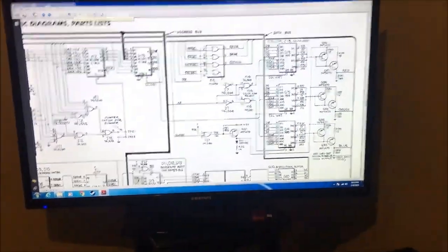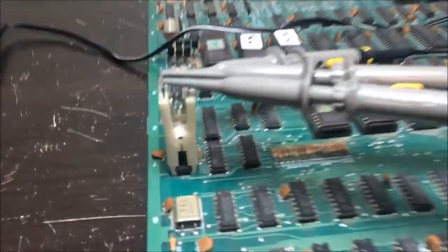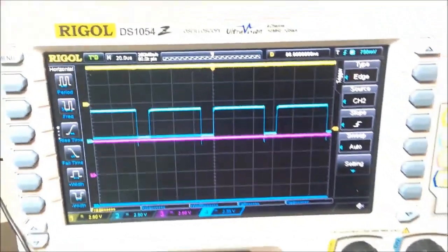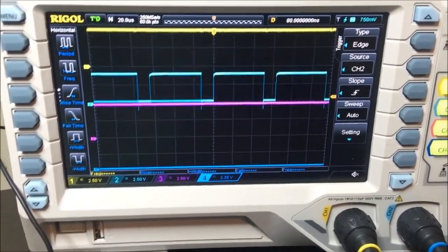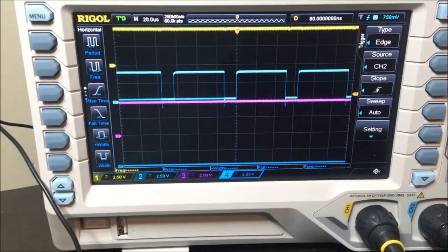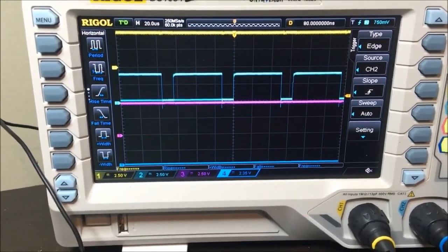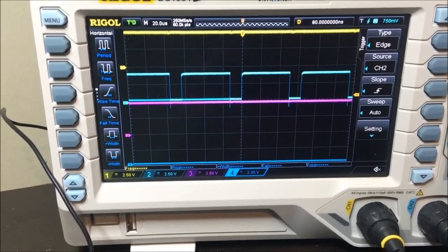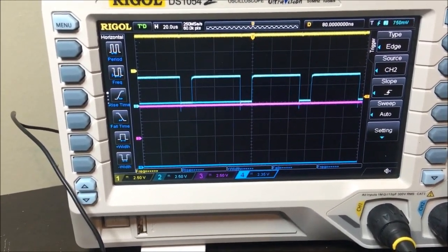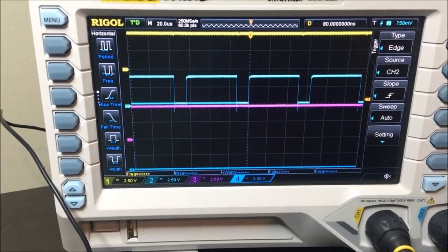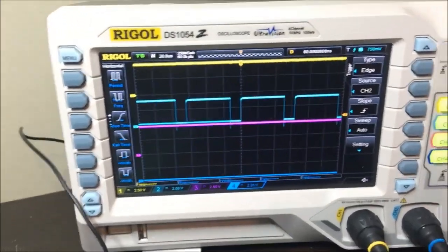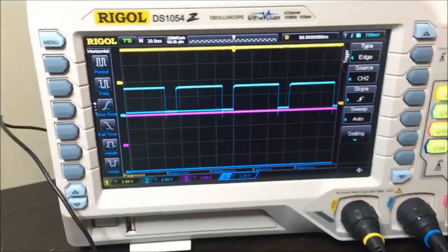So I traced that out on my Qbert board, the bootleg board, to this chip, pins 1, 2, and 3. And here's pins 1, 2, and 3. 1 is tied high, just like in the schematic. The blanking signal is coming in on pin 2, and the output is stuck high. It's an exclusive OR gate, so when both inputs are high, it should go low. And you can see this is running free right now. It is completely stuck high.